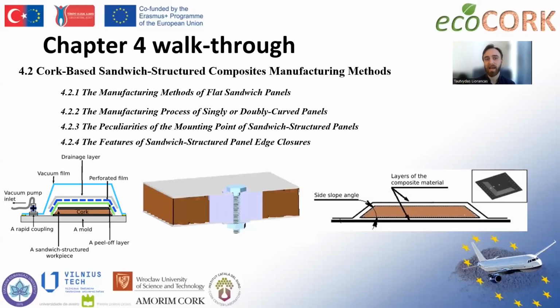Then we will discuss the peculiarities of mounting points of sandwich structure panels. Because, as you see in the middle picture, the core material does not have enough rigidity, and if we tried to mount this plate without any reinforcement, the local contact stress would be too high. So we will discuss the methods to locally strengthen these panels. How can we add inserts or other materials to locally reinforce our panels, so that we can attach